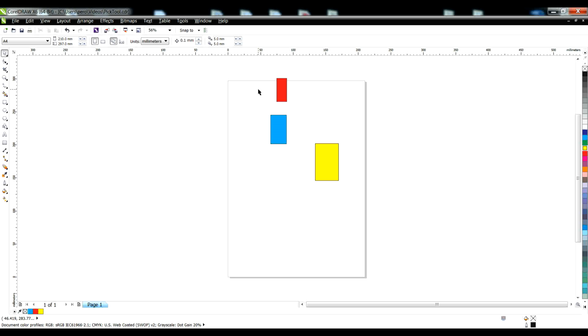If I want to put them in the first position, I click on the first object, I hold my shift key on the keyboard, I click on the second object, and while I'm on this object, I click again with the left mouse key, and now in the field of angle of rotation I double click and type in 0. So if I click on a working area, you can see that our two objects are in the previous position.